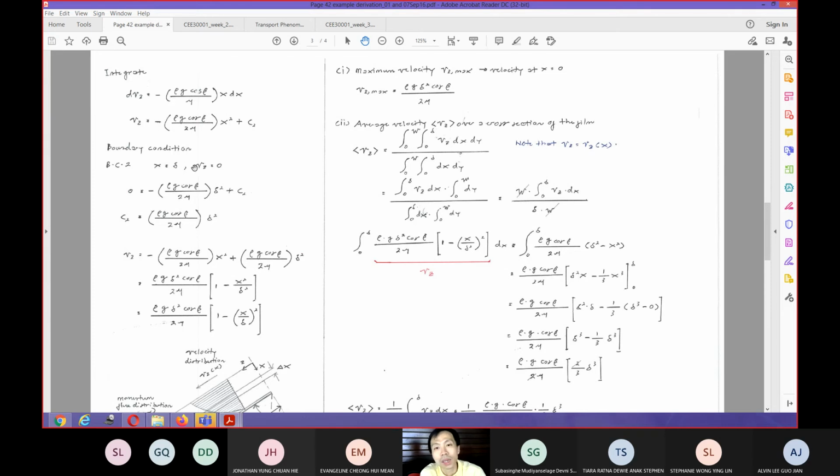Then, like what I told you again, there is a boundary condition on the bottom of your liquid, where it is basically in contact with the solid. So at that particular position we have a no slip condition, where Vz is equal to 0. So let's substitute that into here. We substitute 0, and then we plug this theta into this x. Okay, then we can get the value of C2. So your boundary condition is essentially to get the value of the constant in your ordinary differential equation to make it match with the physical situation.